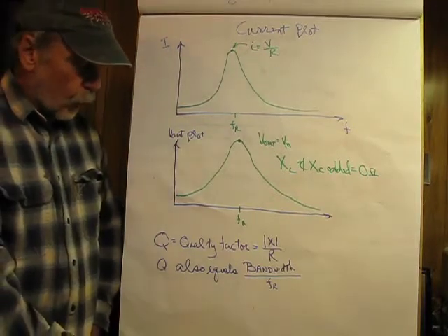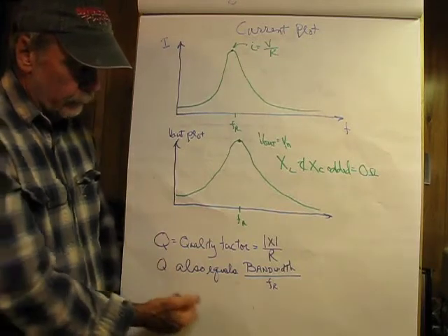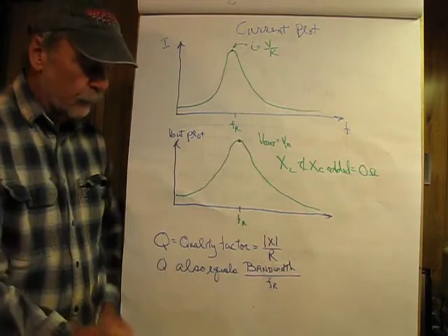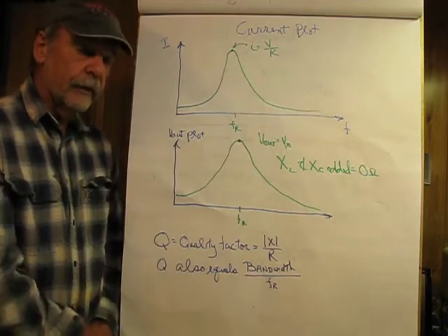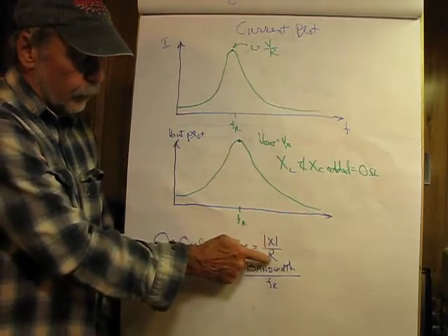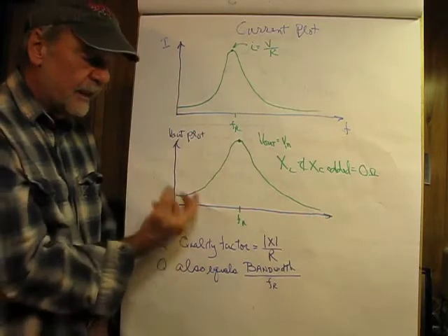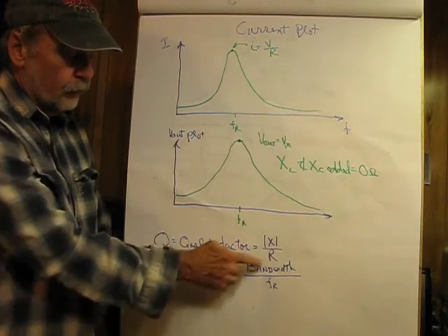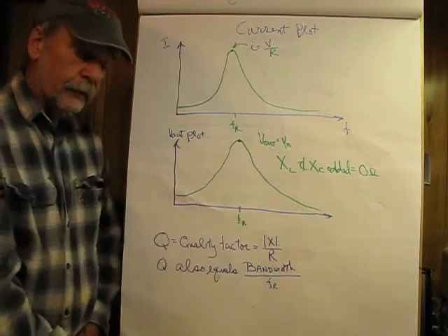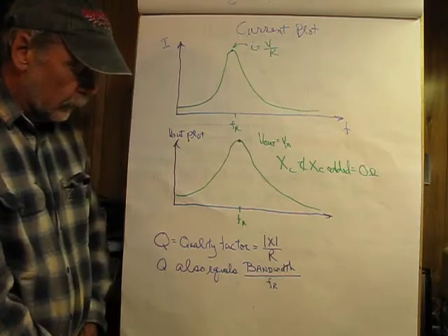So now we come down to quality factor, and that means several things. In short, it's the value of X over R, and I've shown the absolute value there just to be safe and throw out the angle. And the higher the X is with relation to R, the steeper the curve is, the more peaked it is. So if this resistance were higher, what we would see is a wider but less peaked curve. And that has some interesting consequences coming up a little bit later.